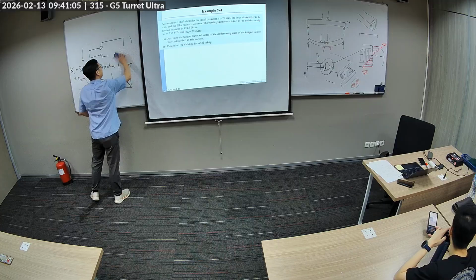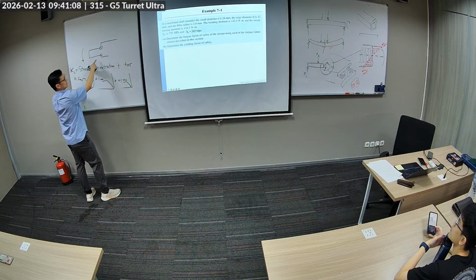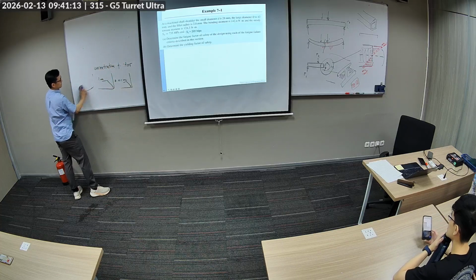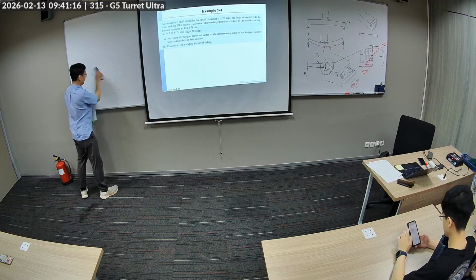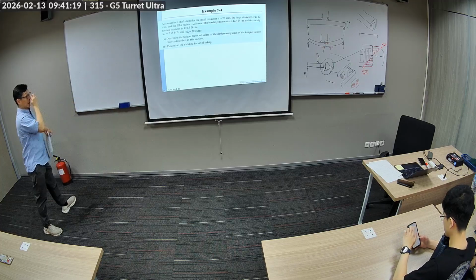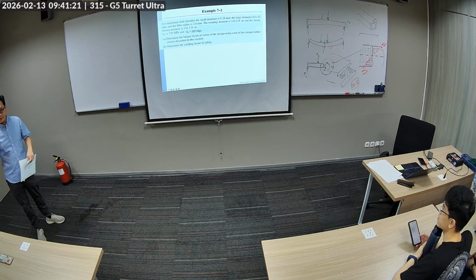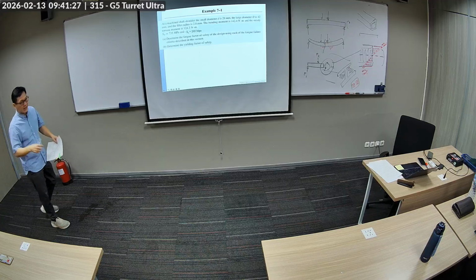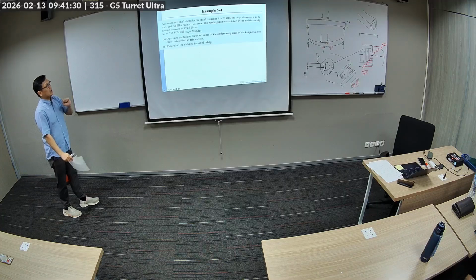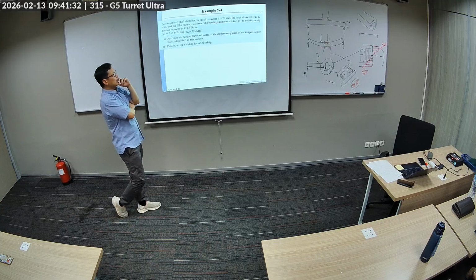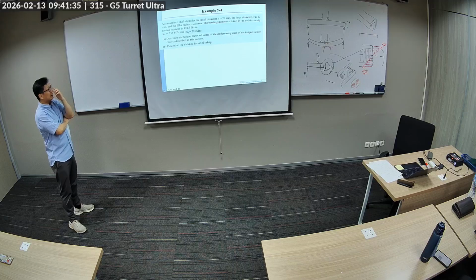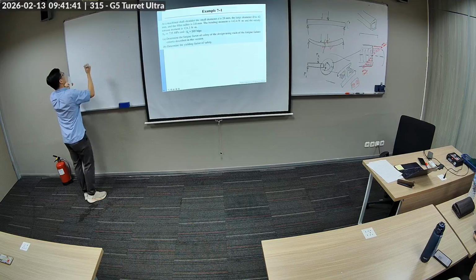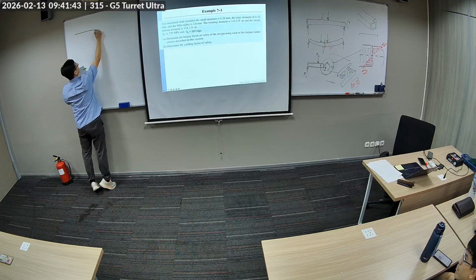Okay, by the way, this is called a shoulder. This is a shaft shoulder. So let's read the problem. And I encourage you to actually write this down. You learn more while you're writing. So take out a piece of paper or tablet. At the machine shaft shoulder, the small diameter d is 28, the large diameter D is 42 millimeters, and the fillet radius is 2.8. So let's say this is a shaft.